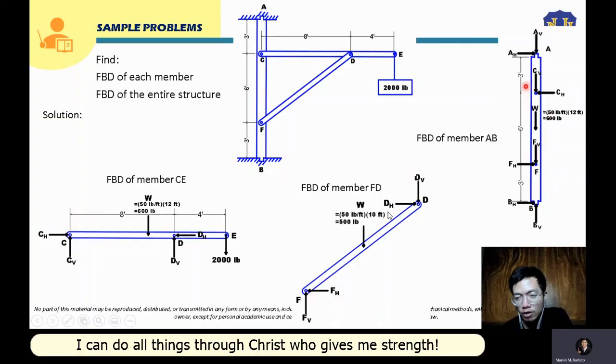Now we're going to show the reaction forces provided by the support. It is supported by a pivot at A and B, so it will just be the same as pin supports. We will assume that our AH will be directed to the right and your AV will be downward.